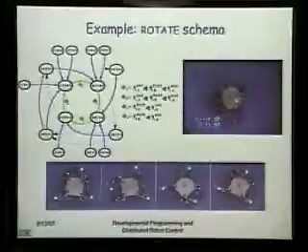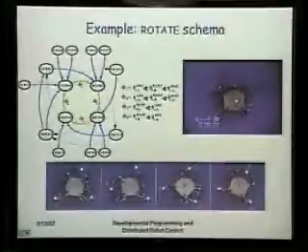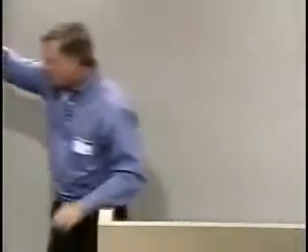And that's a rotate gait. And so what we've done is we've conspired, without the knowledge of the robot, to build a state space in which it was like falling off a log to find a gait that I think the robot will find useful in the future. This is not part of its genetic inheritance. This is something I, as a programmer, told it it should explore that space. You'll find something useful. It puts it away as a temporally extended action by using that relationship between artificial potentials and value functions. That's the program, by the way.